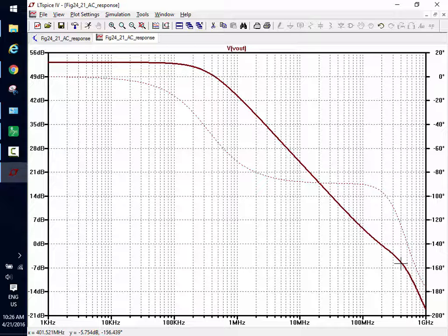Okay. Notice if I go up to F2, phase shift is 135 degrees. Of course it is. We got the 90-degree phase shift from this low frequency pole, and at F2 it adds another 45 degrees, so we get a total phase shift of 135. That makes sense to everyone.